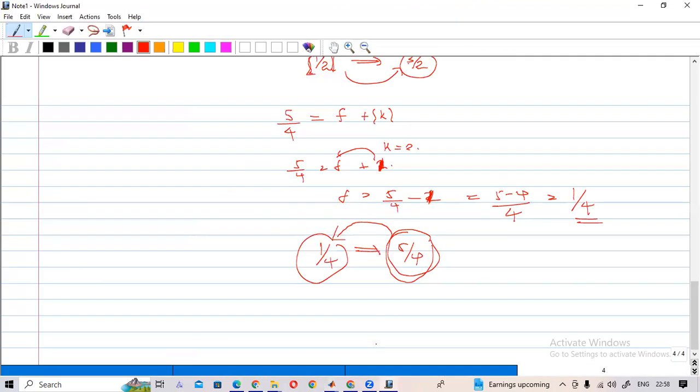So if you have cos 2π10t, and you sample this using 40 hertz, you will get cos 2π(10/40)n. You will get this signal. Now you can see that the normalized frequency here is 1 over 4. So that is less than half. 1 over 4 is less than half.